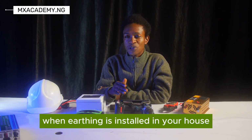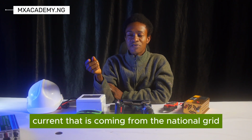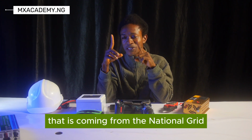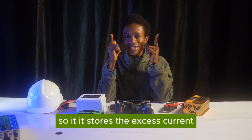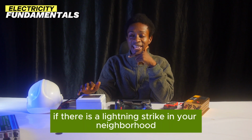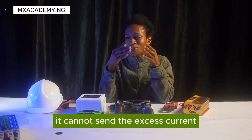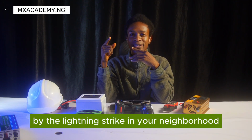When earthing is installed in your house, it sends to the ground the excess current coming from the national grid, or the excess current that results from a fault coming from the national grid, or a fault that happens right there in your house. But if there is a lightning strike in your neighborhood, your earthing/grounding does not have any business with that lightning strike. It cannot send away the current that is generated by the lightning strike in your neighborhood.